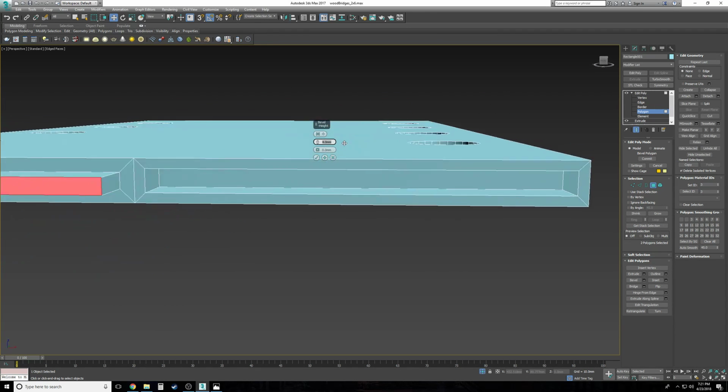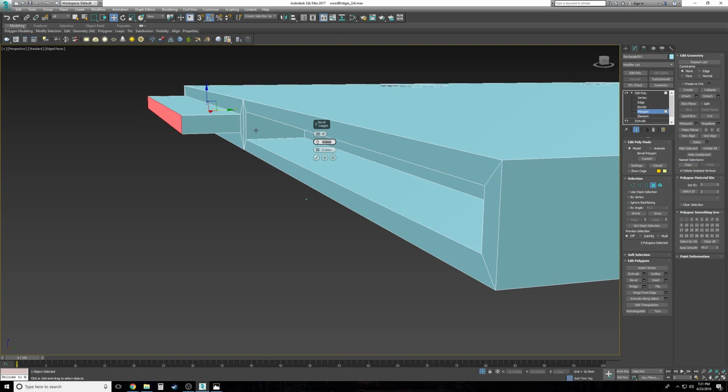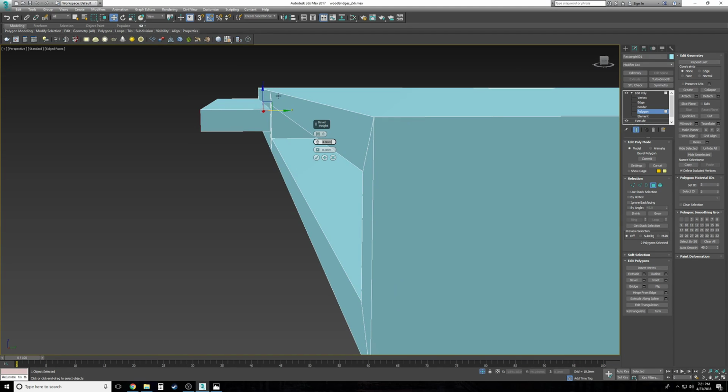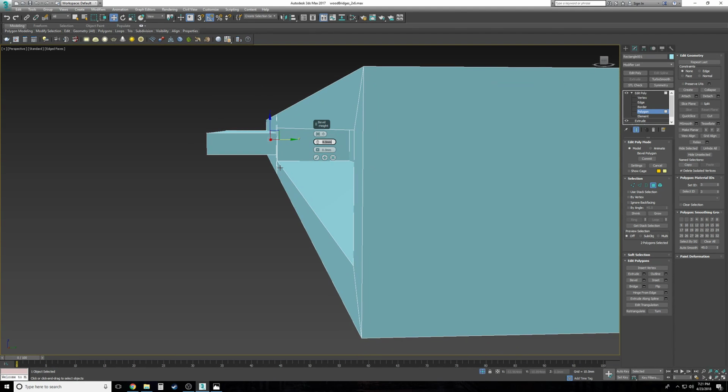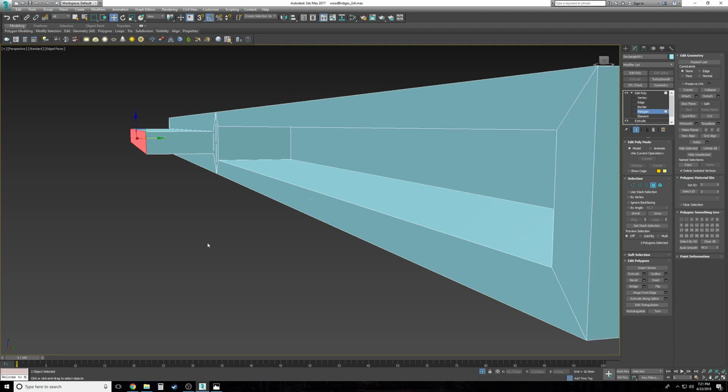If we made it 0.4, there's a good chance that this piece here sits so close to that wall there that there's a little bit of a gap right there. That may not actually fit perfect. The way to do that then is to make it 3.8 or 3.7. And then hit check.